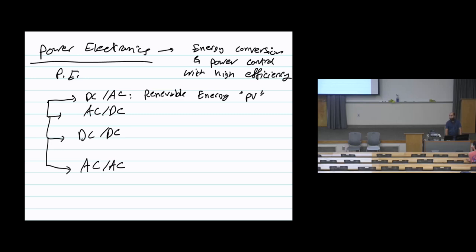So how can I connect this photovoltaics and make this power useful, connect it to the utility grid, or make it useful for our home? We need to connect a DC to AC converter, which sometimes we call an inverter. By connecting the inverter device, I can make this power useful. Since it's DC, I need to convert it to AC, 60 hertz, 120 volts or 240, whatever I need. So I need a device, and in that example it is DC to AC, in other words, the inverter.